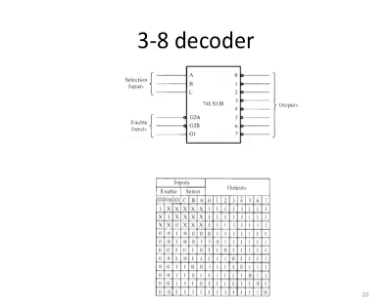Using a NAND gate is a very simple way to do the decoding, but we do have other approaches. Here we can use a 3 to 8 decoder. In this example, this is the 74LS138. This is a 3 to 8 decoder. On the input side, we have selection inputs, CBA.